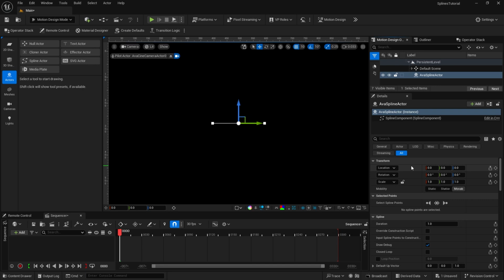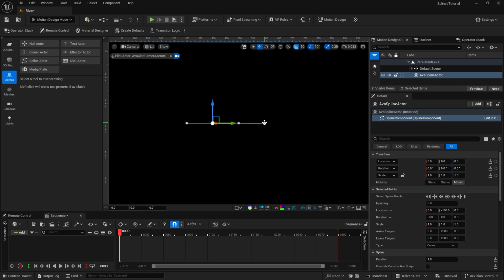The first shape that I'm going to create is that of a shield. In doing that, I should be able to introduce you to most of the properties you'll use in creating these splines. Again, this spline has 2 points. You can click on those points there. You'll see that you have a gizmo and you also have handles with them. The gizmo can be used to move those points in location in the 3D space, and then the handles can be used to shape the line.